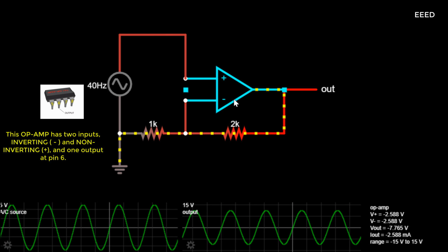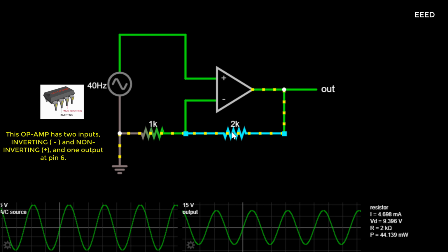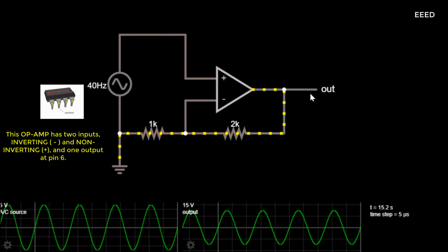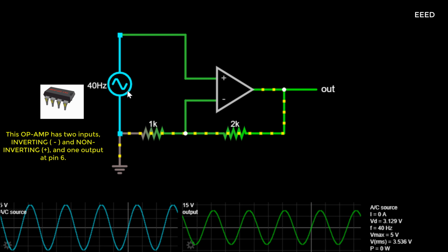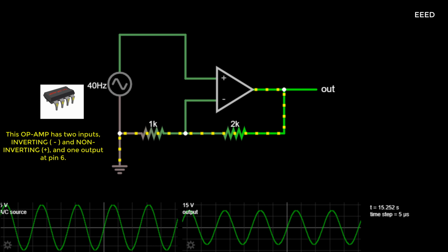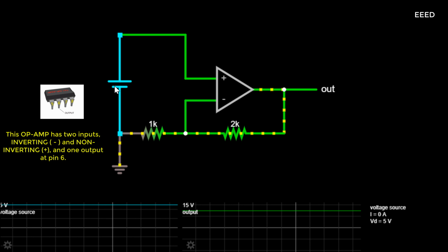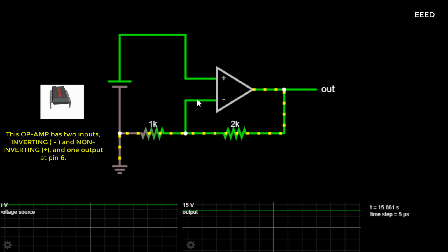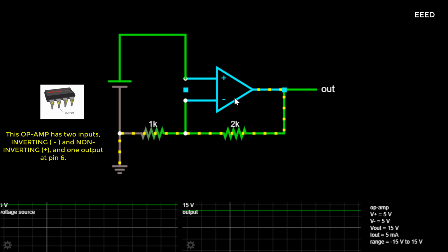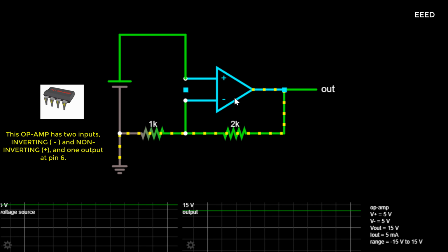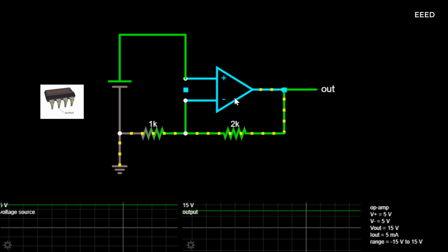Non-inverting operational amplifier. The second basic configuration of an operational amplifier circuit is that of a non-inverting operational amplifier design. In this configuration, the input voltage signal, VIN, is applied directly to the non-inverting (plus) input terminal, which means that the output gain of the amplifier becomes positive in value, in contrast to the inverting amplifier circuit we saw in the last tutorial, whose output gain is negative in value. The result of this is that the output signal is in phase with the input signal.